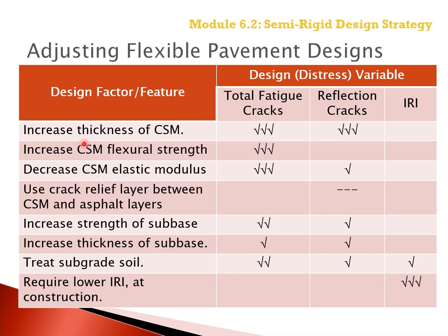And again, the definition of the number of checks that were discussed for flexible pavements also applies to semi-rigid pavements. So in summary, if we increase the thickness of the chemically stabilized layer, there's a significant effect on total fatigue cracks, whether they're reflection or of the chemically stabilized layer, and also on reflection cracks.